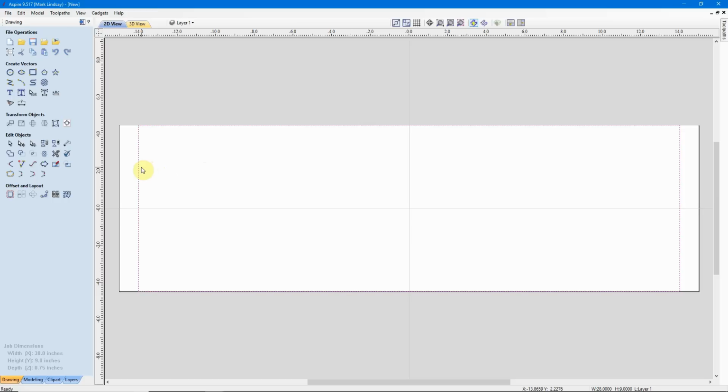So what we'll do is we're going to do some node editing on this rectangle because I don't want a rectangle. I want that rustic kind of sculpted weather-worn look. So with my rectangle selected, I'll type the letter N on my keyboard to go into node editing mode. And when I do that, we bring up these 4 points or nodes out here on the corners.